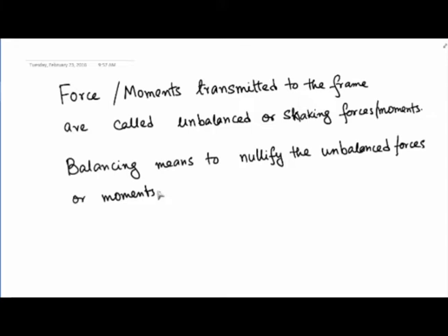of the machine. It is harmful in terms of, let's say it's a grinding machine, and if you have a large amount of forces which are getting transmitted onto the frame of the machine because of the grinding wheel which is operating, then what will happen is that the job will start vibrating, and if the job starts vibrating, you will not be able to get a good quality of finish. So whenever there is a large amount of shaking forces which are getting transmitted to the frame of your machine, there is something detrimental about the quality and performance of the machine, other than the fact that the machine will reduce in terms of its life.